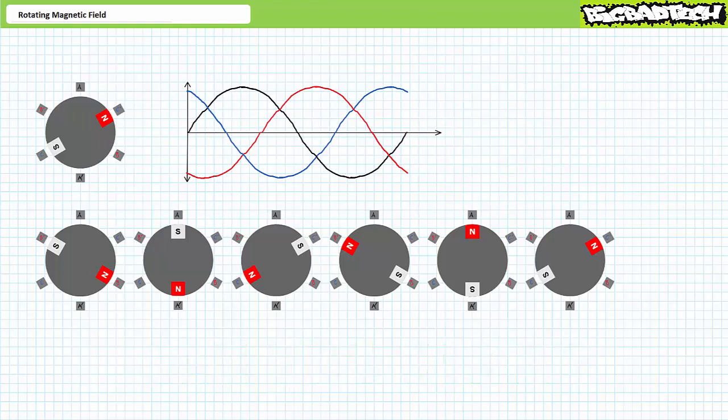A single pole pair per phase stator produces a rotating magnetic field that necessitates one complete cycle of sinusoidal AC to complete a full revolution. If you think about it, a single pole pair per phase motor has 6 check-ins along the way. Technically 3 because they always occur in pairs, but I'm counting them as 6 because each end can assume north or south polarity, depending upon voltage polarity, and there's 6 total positive and negative peaks in a full cycle of 3-phase AC. L2 negative, L1 positive, L3 negative, L2 positive, L1 negative, and L3 positive.